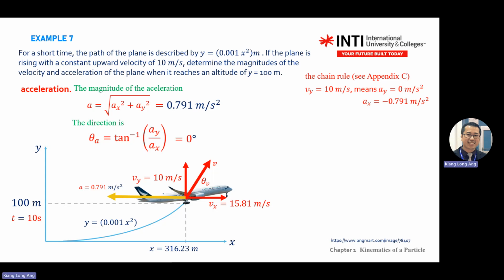And then we go to curvilinear motion. In curvilinear motion, what is important is the curve. Every curve has a center. When you have a tangent direction at a position, let's say A, your velocity will be tangent to the curve. And your acceleration will always point toward the center. So this is how you draw the vector diagram when it comes to curvilinear motion.